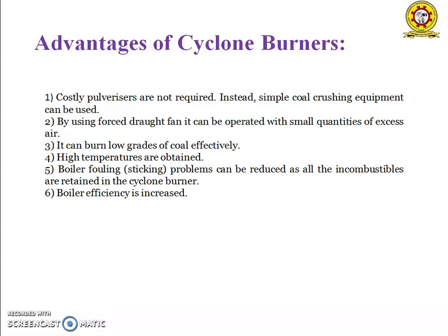Another type of burner is the fuel oil burner. In fuel oil burners, vaporizing or evaporating type burners and atomizing burners are used. Atomizing burners are again broadly classified into steam burners and mechanical atomizers, and there is also a fuel oil and gas supply arrangement.